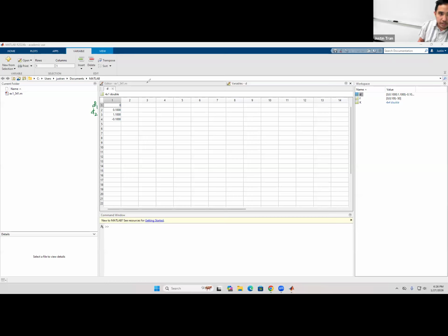So that our D2 in here is 0.1 meters. And so you can see that our node 2 does not really change in position all that much, which makes sense because if you think back to the problem, we have kind of opposing forces. We have one force that's pointing to the right, another force that's pushing it to the left. And so it kind of makes sense that those two kind of cancel out and we don't really have that much deformation there, okay?